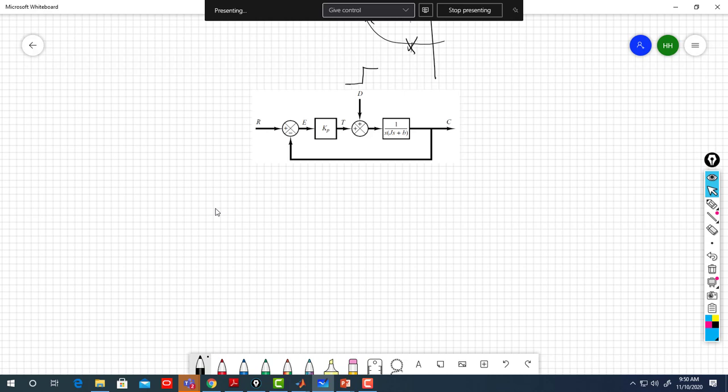So in the joint control problem you need to control the joint angle, and you will most likely have disturbance on the system. What if I have a proportional controller also? Will that eliminate the disturbance, or does proportional control not cancel disturbance? What do you think? So this is a question: how will the error be affected by disturbance? It doesn't reject. Proportional control doesn't reject disturbance.